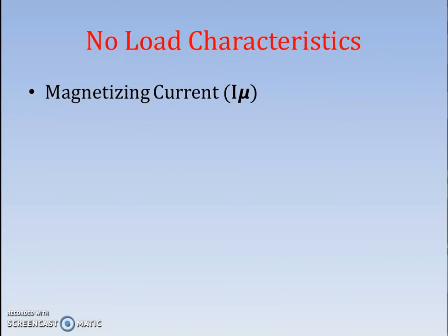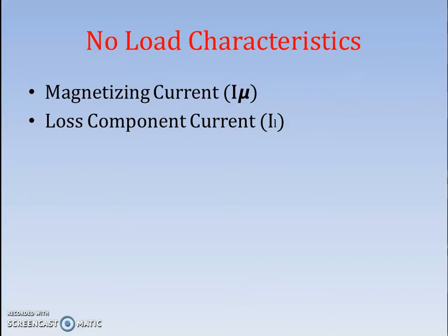One is the magnetizing current, which is required to generate flux or magnetic field. Another is the loss component, which is required to fulfill the losses during no-load condition.